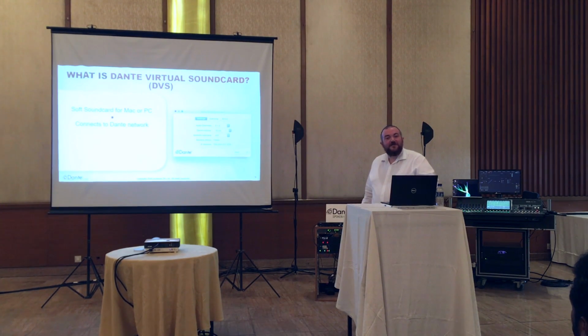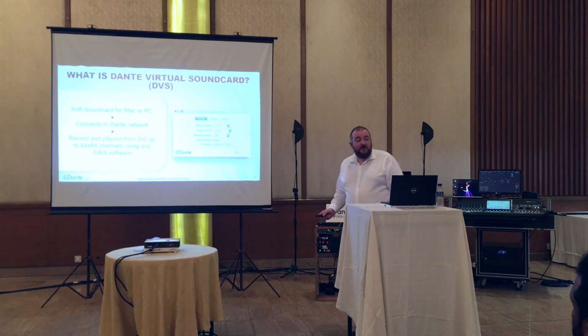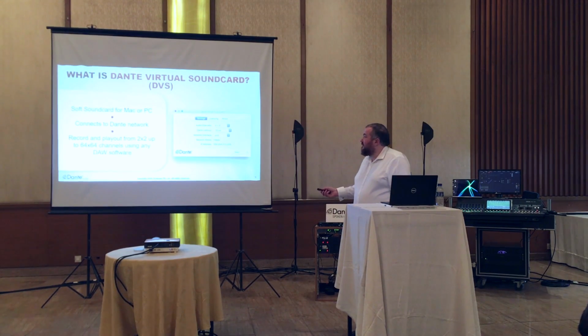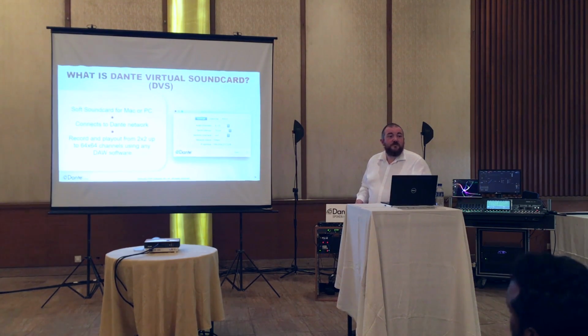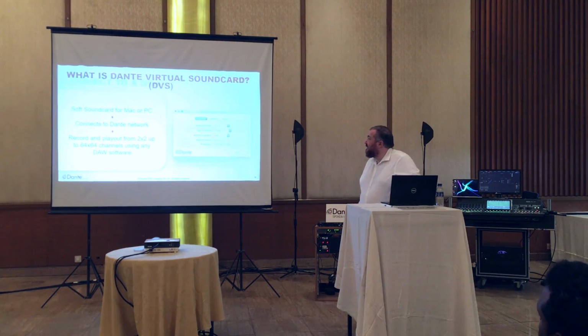This basically presents audio channels from your computer as normal Dante audio channels that can interact and be routed and patched from and to existing Dante network devices. And you can record and play out from as few as 2x2 up to 64 in 64 out audio channels using normal digital audio workstation software.